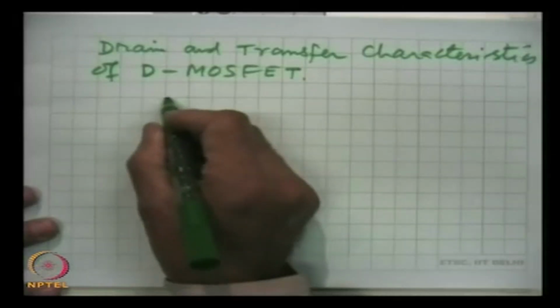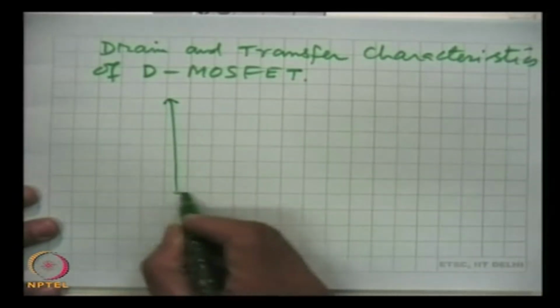We talked in the previous lecture that because of the oxide layer which isolates the gate electrode from the semiconductor, in the depletion MOSFET we can apply a negative voltage, 0 voltage and a positive voltage. When we apply the positive voltage to the gate, it will induce negative charges in the channel region, and hence the conductance will increase, and it will keep on increasing when we increase the positive gate voltage further. So, the drain characteristics are like this.